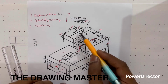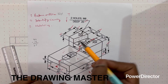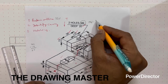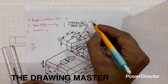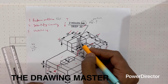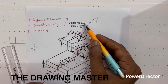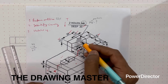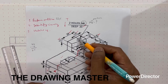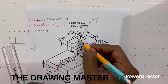One more thing. What about these two holes, M6, 20 deep? First let's understand what is M6. M stands for metric. So here basically we have to insert the screw of M6 size, means metric thread having 6 mm nominal dia. So here this diameter should be at least 6 mm to accept this screw. So here the dia should be 6 mm.